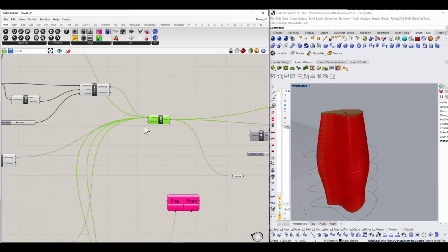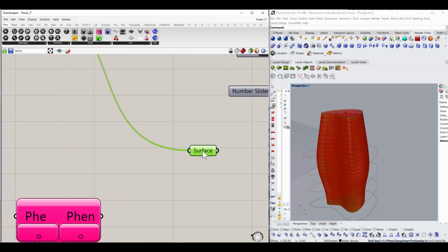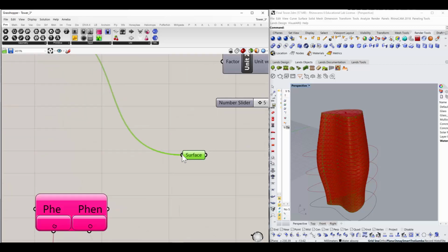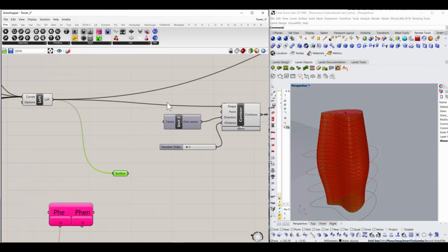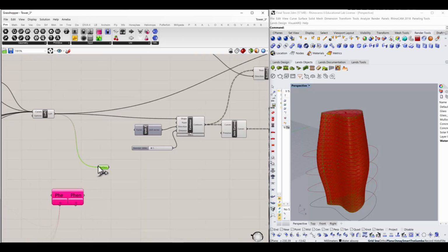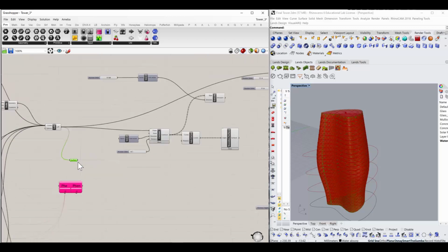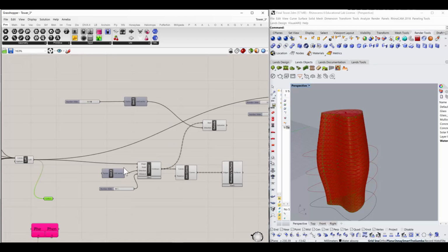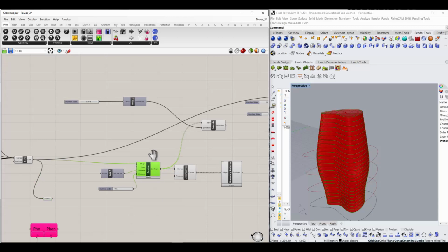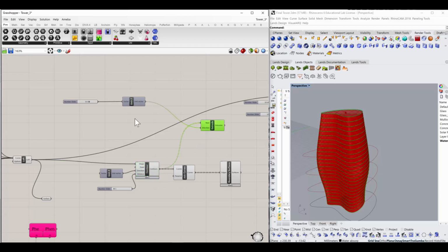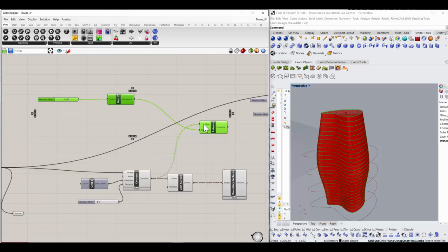Once I loft all these curves, I take the surface. Yeah, this is the surface. I've kept it separately. The same surface I've used here to make contours, and using these contours I have created an extrusion. So this is done for making the floor slabs.